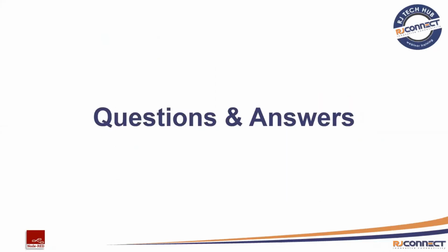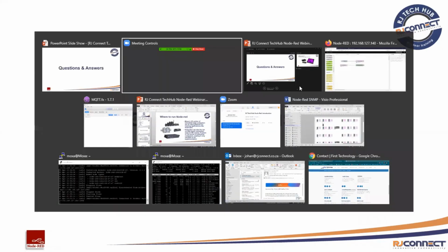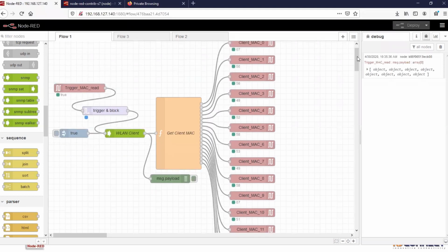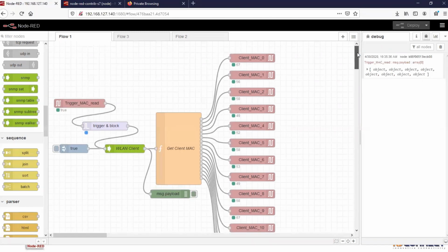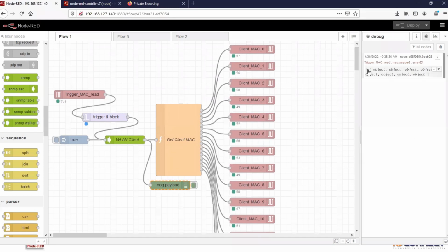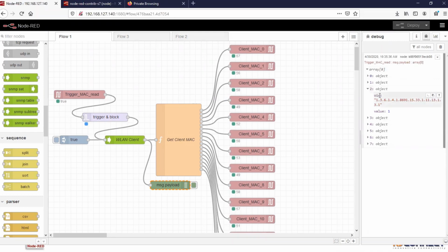Yes. So we use NodeRED very successfully for many customers that have unique solutions. We're busy with a customer right now. I think Johan just showed you the one little flow there, where the customer requires to connect to our AWK radios and have the information available in a Rockwell EtherNet/IP PLC. And so we've developed this flow in front of you right now that allows a customer to read which clients are connected to the AP via their MAC address, and decide who should be on the radio and what control they have. This was only achievable either by a lot of quite complex PLC coding, or by using NodeRED on one of our UC computers and having a nice flow.